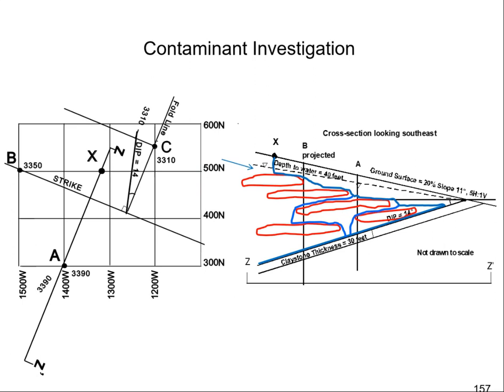Well, if you have a leaking underground storage tank, what's the first thing you do? You remove the tank. You yank the tank, and then you take with it the most contaminated soils immediately adjacent to where the leak was. So 2 of our answers we can throw out because they don't say take the tank out, and taking the tank out is what you always do when you have a leaky tank.